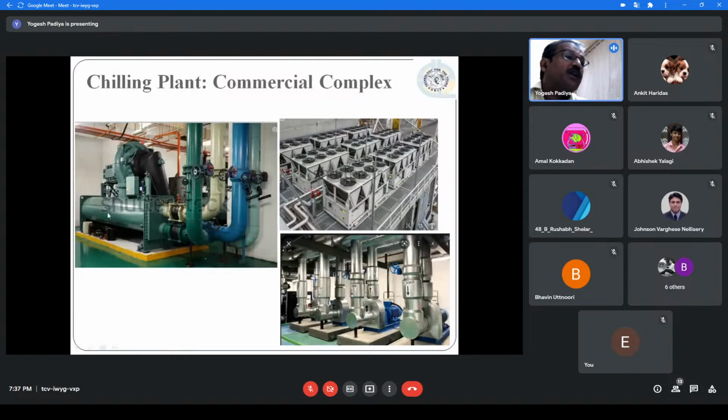So I have my evaporator coil, and on the other side a condenser coil. Through the evaporator, I am passing water. Hot water is coming and getting cold. Now this cold water is going to the AHU. I will tell you how the AHU will work. And here in the condenser, the cold water is coming and getting hot. This hot water is coming to a cooling tower. Through the cooling tower, the water is being sprayed, and once it's sprayed over the cooling tower, the water gets cooled. So there are pump sets placed all around.